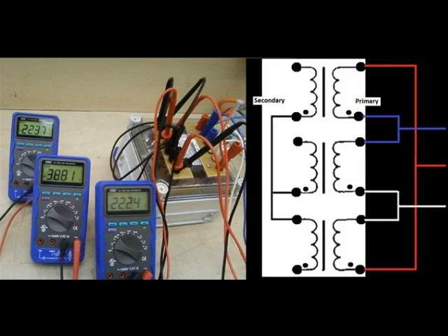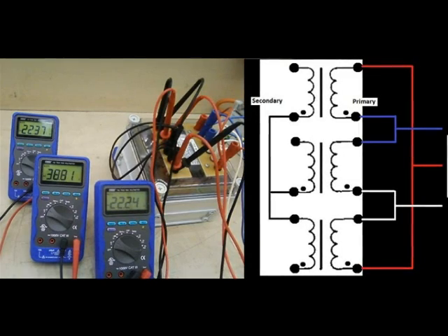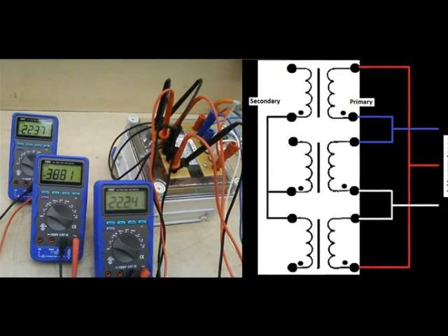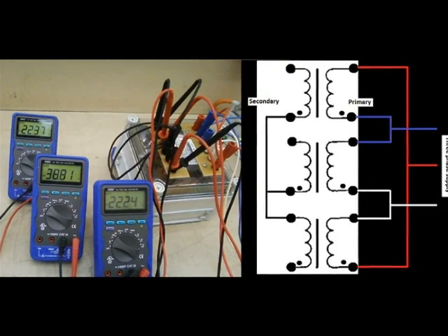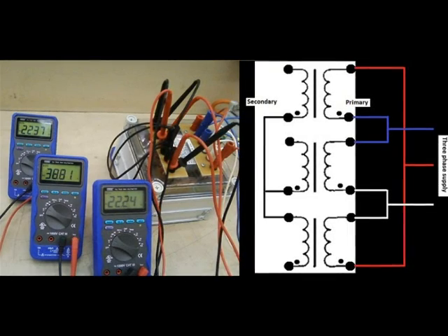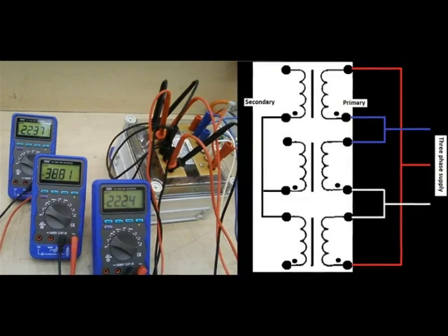So this would cause grave problems, of course. If you try to run a motor or any other balanced load, you would have a growling hot motor and so forth. So it's important that all the voltages are checked once you've done your connections.